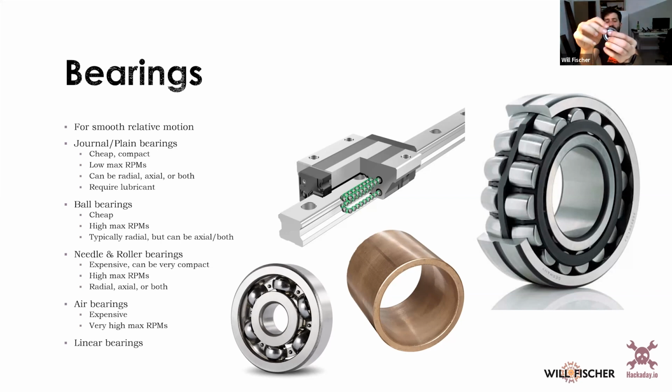And I could probably do the same radially. So you can see that it kind of falls apart if I don't have it in a thing. I could probably put 100 kilos of load radially and it'll still rotate freely. So that's really cool that I can do it. It only does axial load in one direction, right? Like it literally falls apart the other direction. These are pretty expensive. So this bearing, I think, was about 15 euros. So they're awesome, but they're expensive.